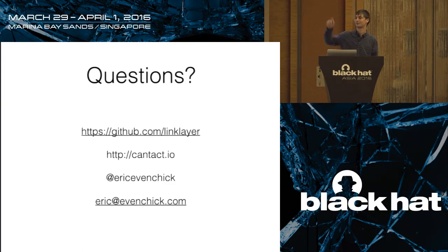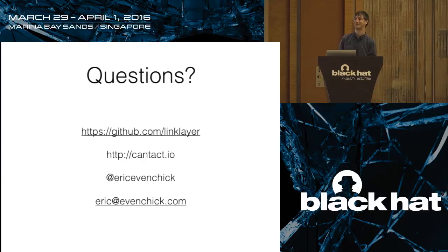Yes? Can you give some examples about the scripting ability? Yes, my favorite example of scripting is the silly one of doing a denial of service. I didn't talk about the electrical characteristics of CAN, but really simply, low IDs have priority and they win. So if you send the message with ID 0 really, really fast, you will basically shut down most cars. That's one really fun one that is like 3 lines of code.